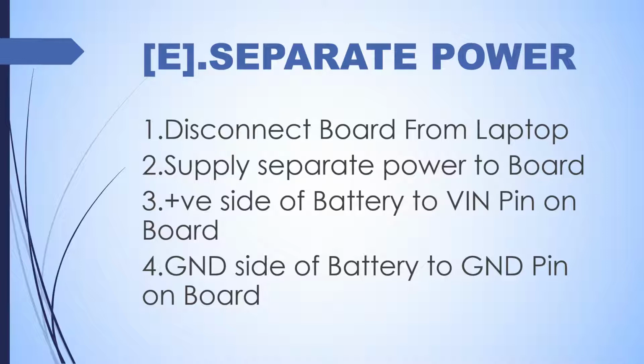If you don't have a separate power supply, then no problem, you can take the power from the laptop also. Then the positive side of the battery, this is important, which I discussed in the previous demo. The positive side of the battery, you must connect to the V in pin on the board.